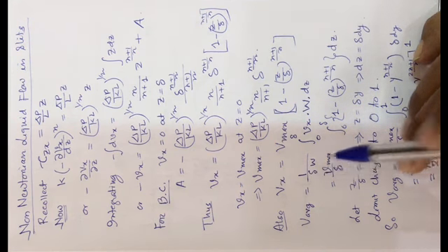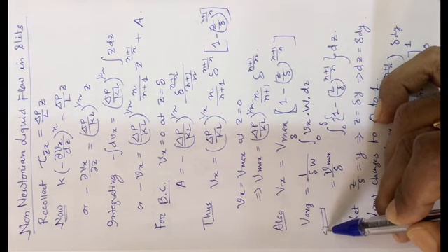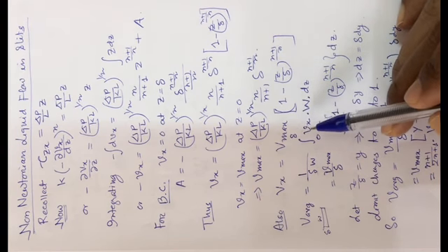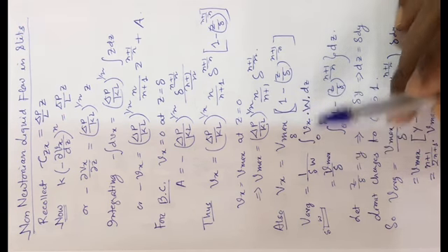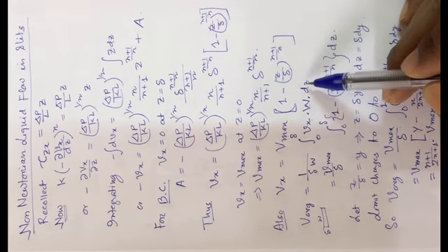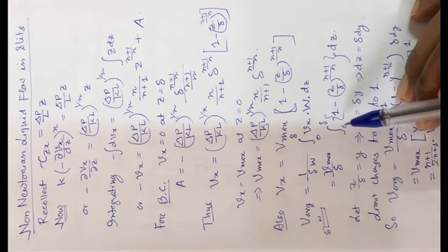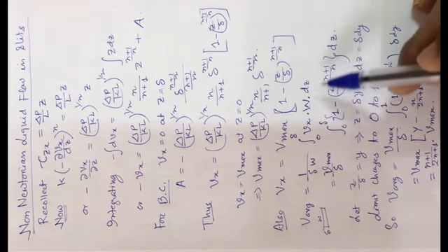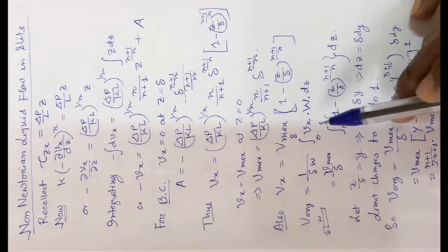So this flow area is basically delta and w, where w is the width of the slit, the same w. Then we integrate in the z direction. Vmax by delta, this particular factor Vmax is independent of position, so it can be taken out. Only the dependent part will be 1 minus relative position. So we are integrating it from 0 to delta.